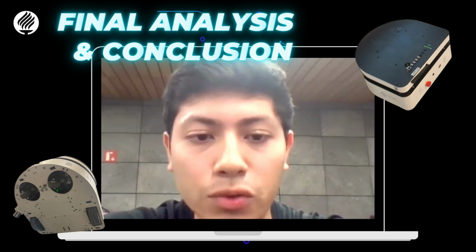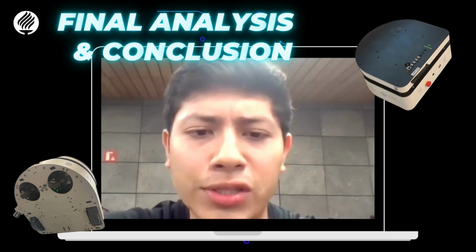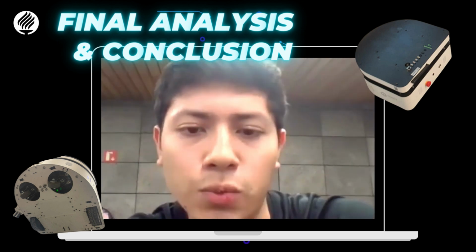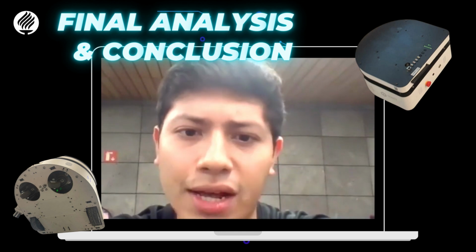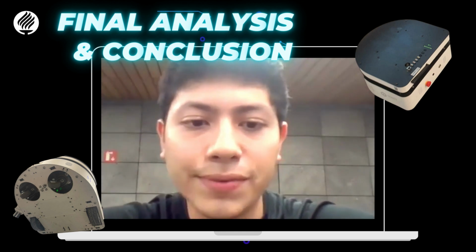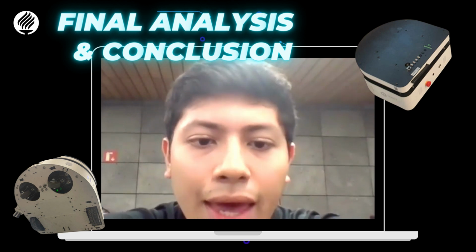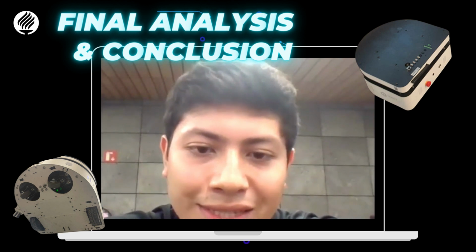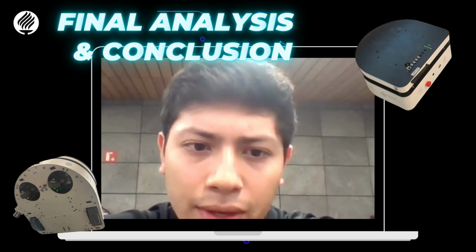To ensure high precision in simulations like the ones we conducted in this challenge, it is crucial to calibrate the robot's linear and angular movements, and consider velocity and the achievable distance without abrupt braking.